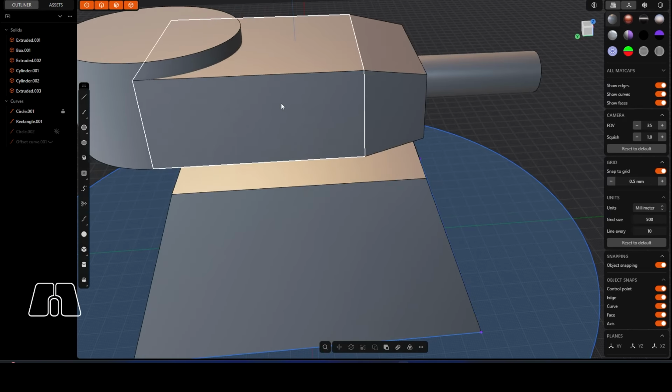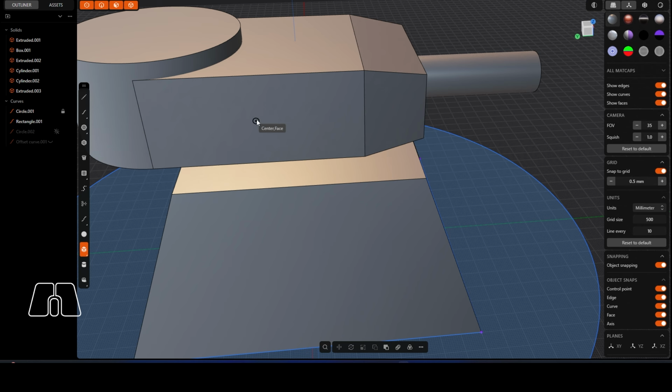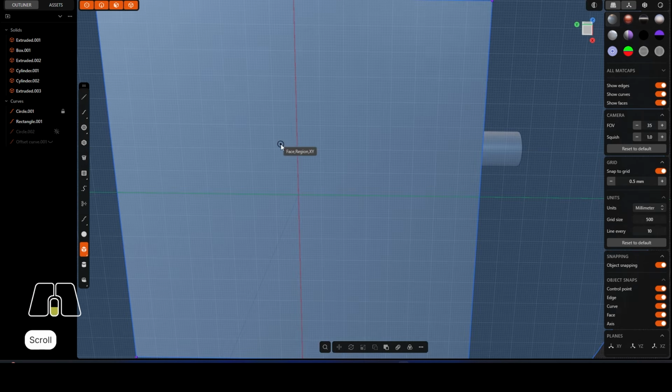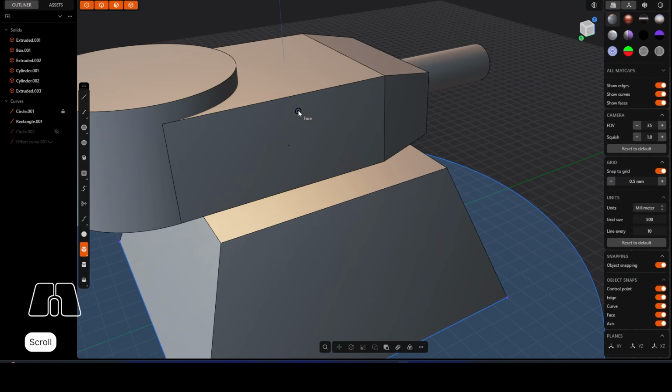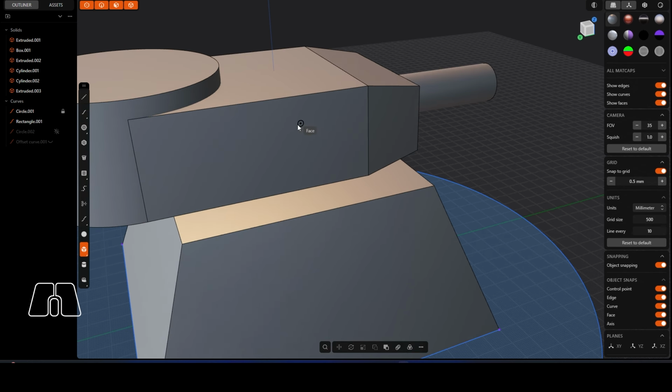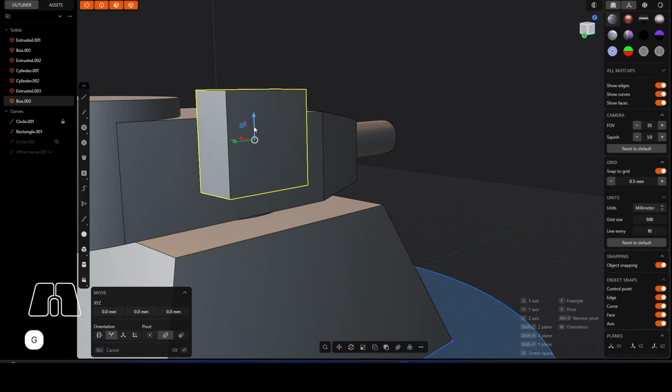Now, Plasticity is really good in the sense that it lets us draw things on directly. So we can do a rect box center, you get your corner box or your 3-point box as well, which is probably advisable. Maybe we'll do this one here. So we can just jump into that perspective view, and then maybe, I don't know, let's have a look, maybe to the front here. We're going to add something like this, and we're going to use B just to add it in. I think that'd be okay. Let's use the G key.